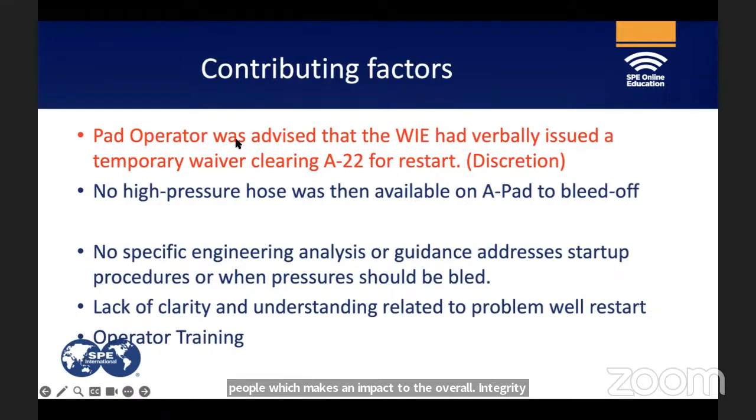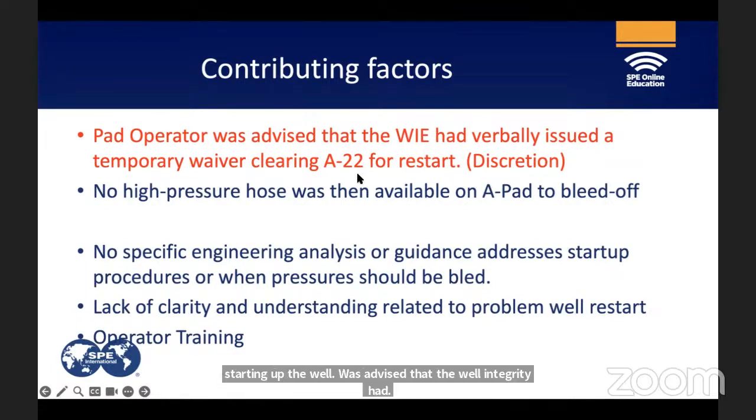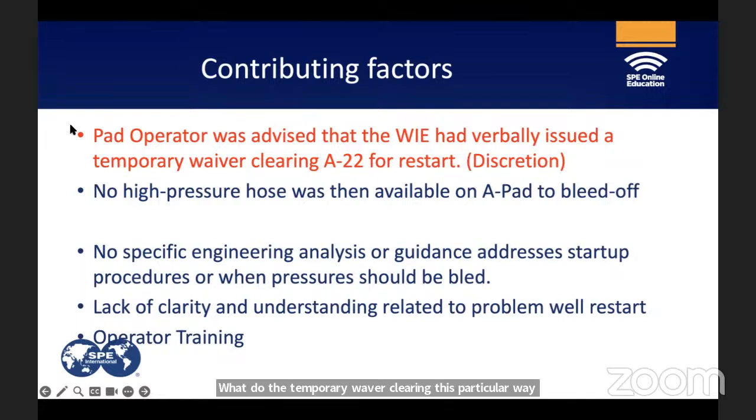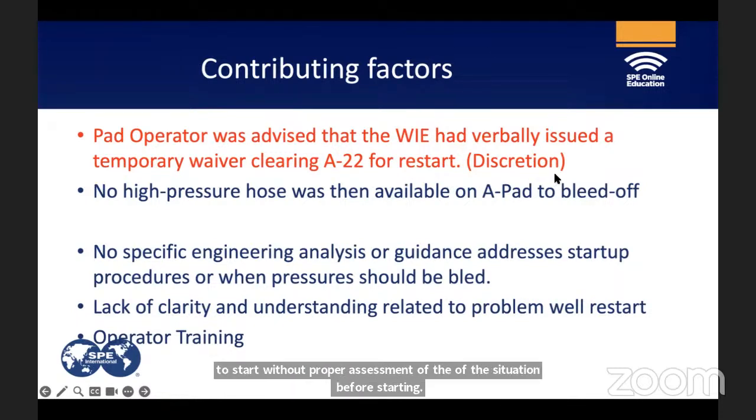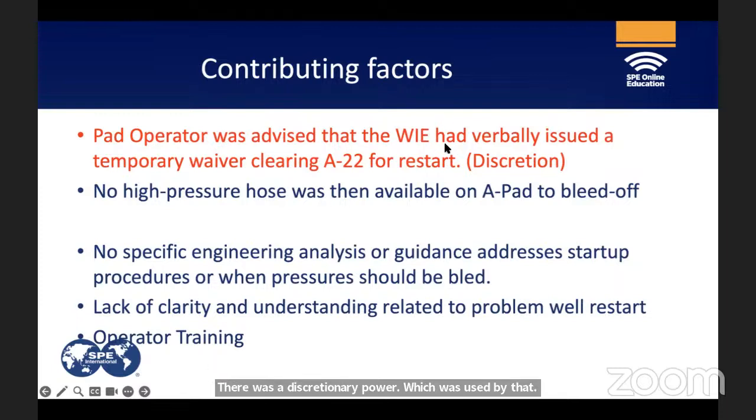The pad operator who was at the site starting up the well was advised that well integrity had verbally issued a temporary waiver clearing this particular well to start without proper assessment of the situation before starting. So there was a discretionary power which was used by that engineer to convey the message to the operator, and no written communication was there.